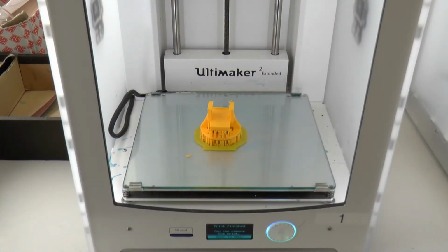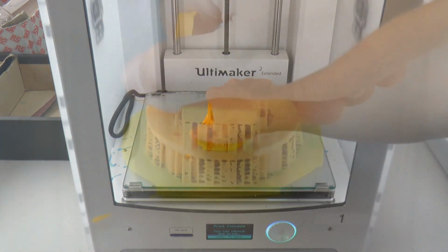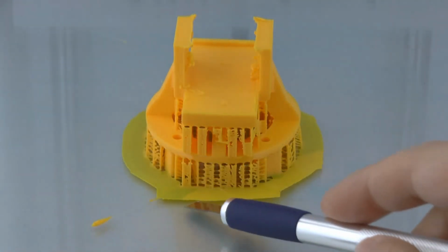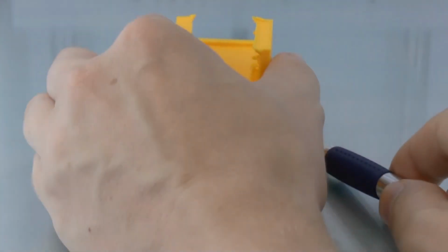When your print is finished, it is likely to still be firmly adhered to the build plate. If it is only just finished, it is also likely to be hot, so it must be left to cool thoroughly. A technician will carefully remove the item. Please do not attempt this yourself, as the build plate is very sensitive to force displacement. Depending on your design, you may now have some work to do removing the support and scaffolding material.